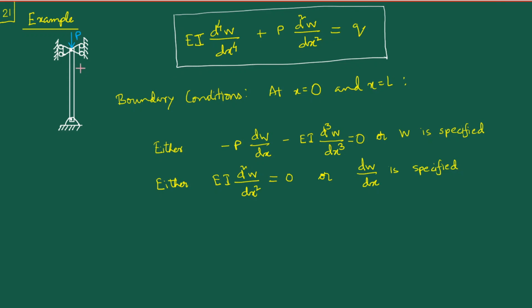And in the process, we want to get some insights into the deflection, because the governing equation that we have here certainly involves the variable P, but it is a differential equation in terms of the deflection W. So let us see what insights we can obtain about the W also. Our immediate job now is to understand the specific boundary conditions which will be applicable given this kind of a physical setup.